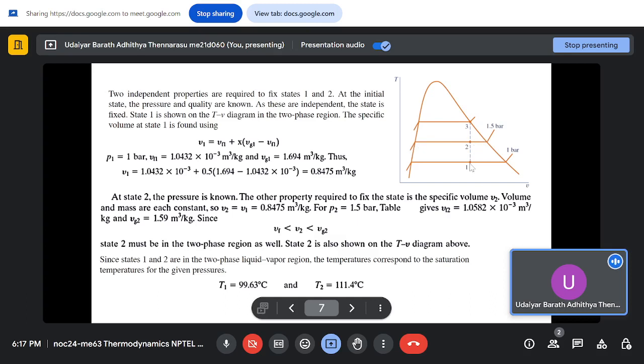You see, from saturated vapor and saturated liquid, the length between the point and the dome is different. At higher pressure, you are moving closer to saturated vapor. And when you reach state 3, you are fully at the vapor dome, at the saturated vapor state.